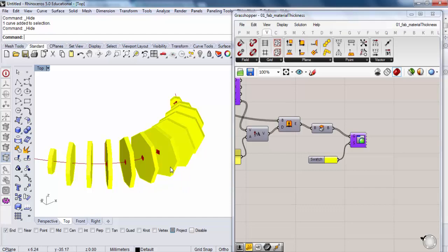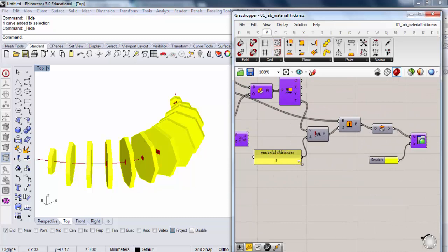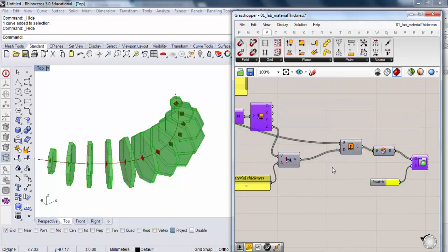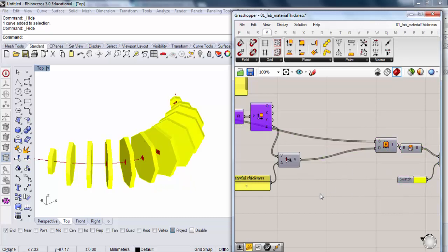Yeah, it's necessary sometimes. Okay, so where are we up to? I just did the standard method of extruding this, but there's other details that you can go into. Say, for instance, the offset of the thickness of the material. Do you want it centered to your plane, or do you want it offset slightly, or whatever? So I'll just center this